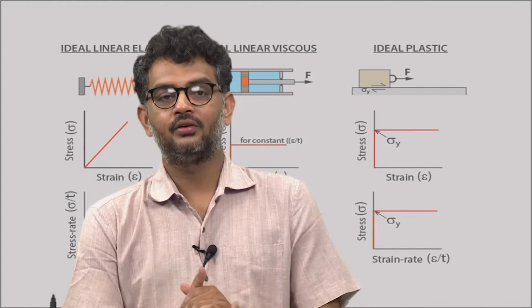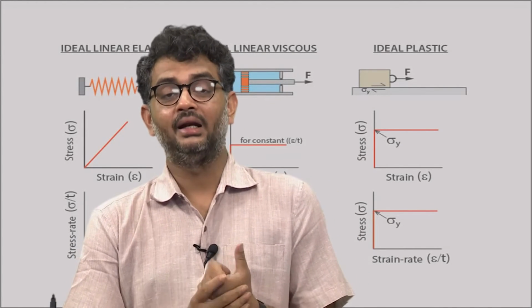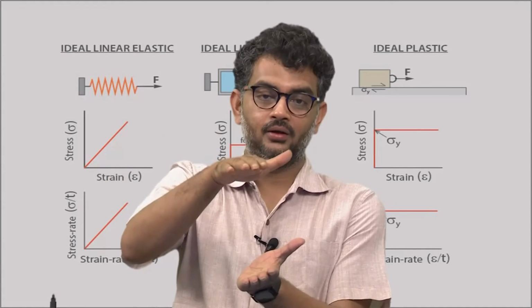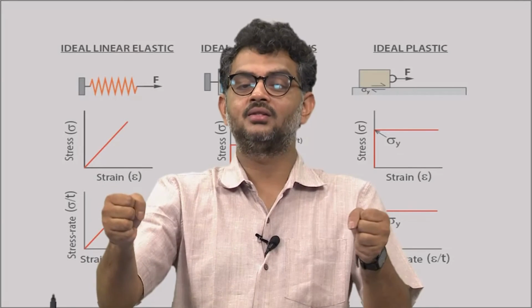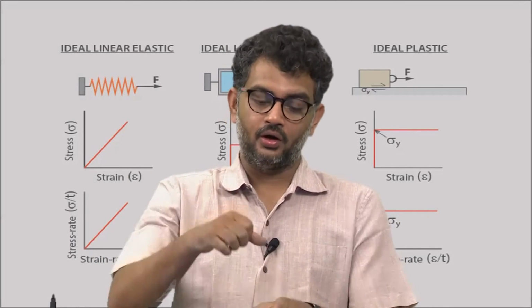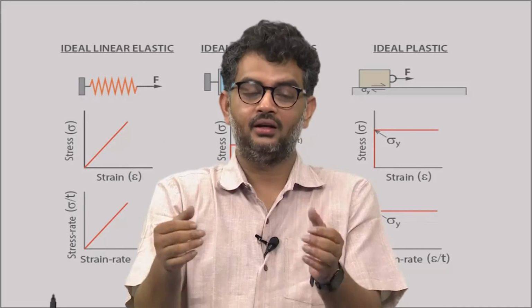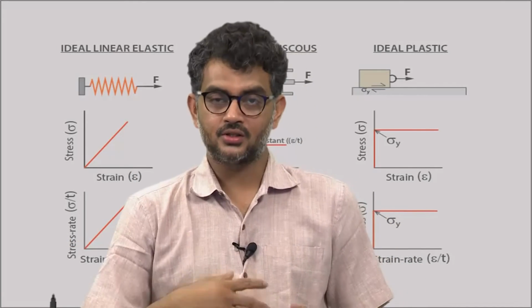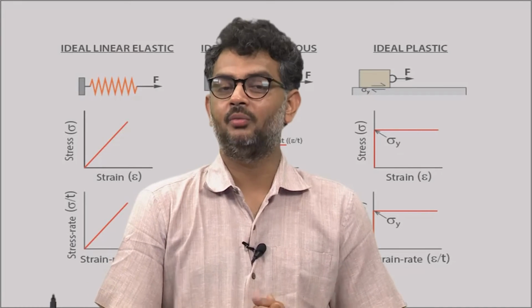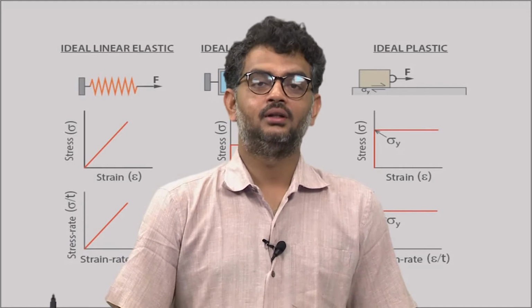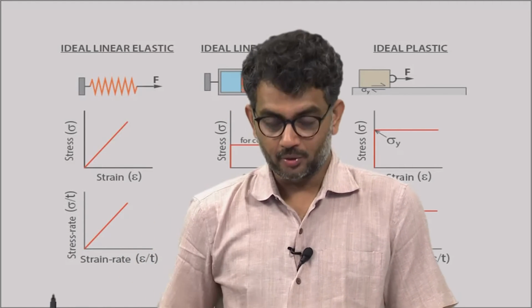There are some other materials that do have a negative Poisson's ratio. That means, if I compress in this side, instead of expanding in this side, they can also shrink, or if I extend something in this side, instead of compressing in this side, they actually extend. These are some complex composite materials. Honeycomb is one of the examples that you can think of that do have negative Poisson's ratio.